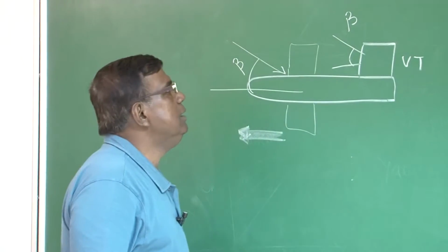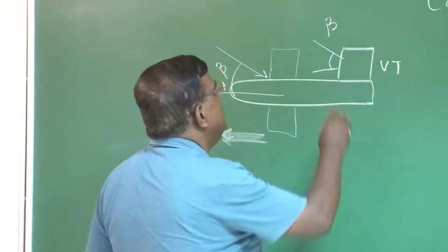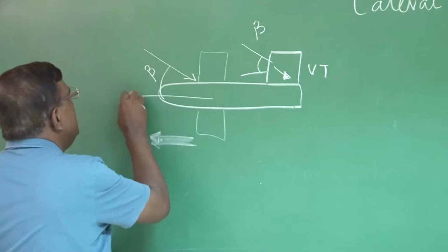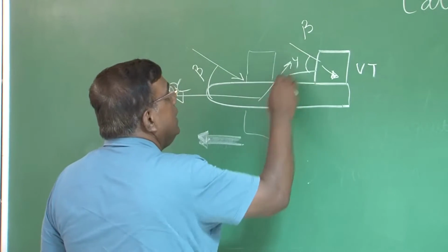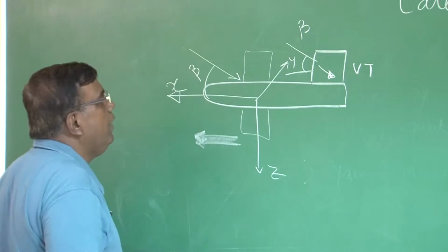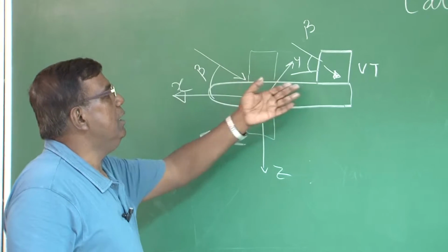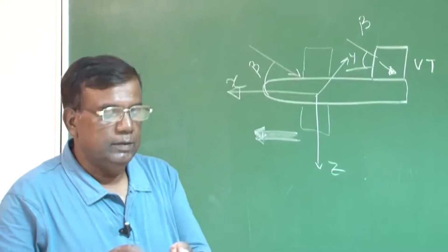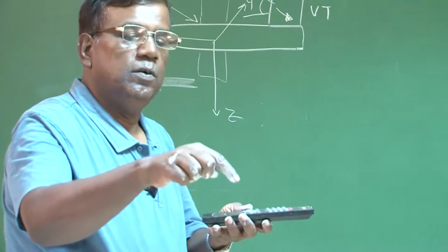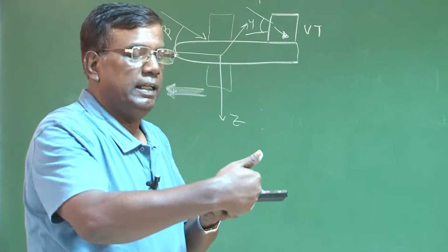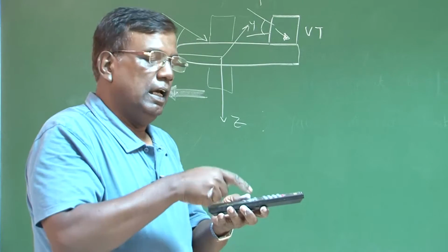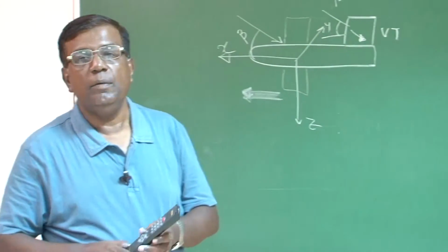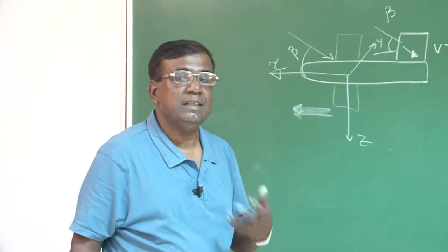We will discuss those, right? But whatever beta comes, that will give a force this side, and as far as our axis system is concerned, if it is x, it is y, and it is z, then you will find that for a positive beta, the force along y direction will be negative by this convention. That is, this is x, towards you is y, and this is z. If there is a beta like this, the force is in this direction and y is in this direction. So, for a positive beta, the side force will have a negative sign. Okay? This is because of our axis system.